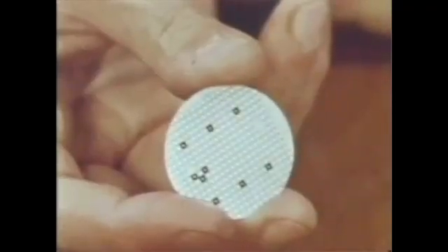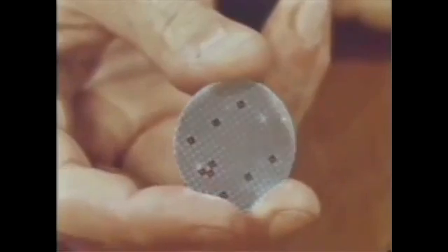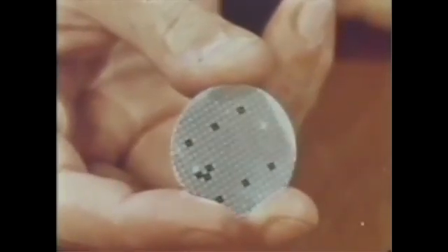The series of schematic operations taking place on one structure that you just saw actually takes place across a whole wafer. This results in a wafer containing many integrated circuits, up to 1,500 of them. Now comes the electrical testing of this wafer. Jim, can you take over on this part?